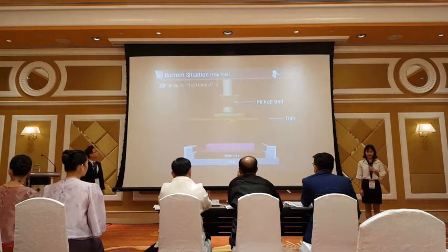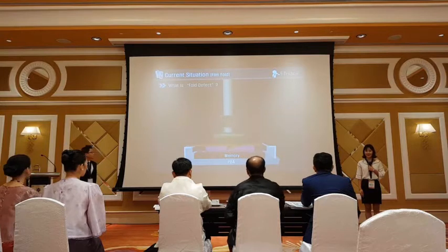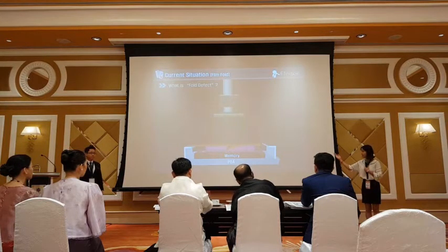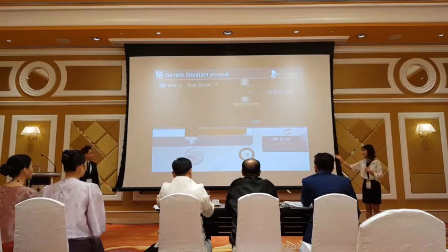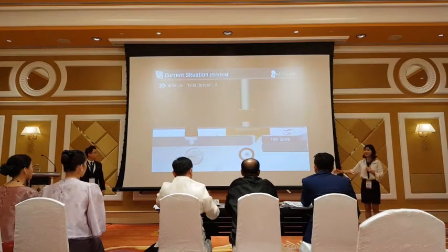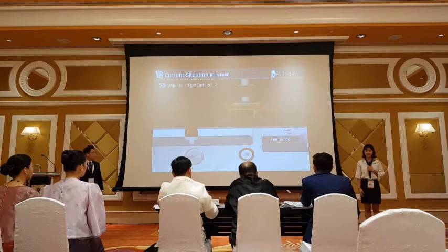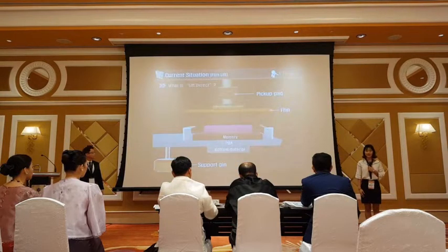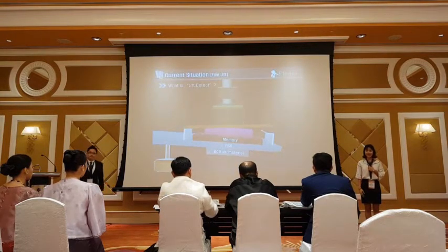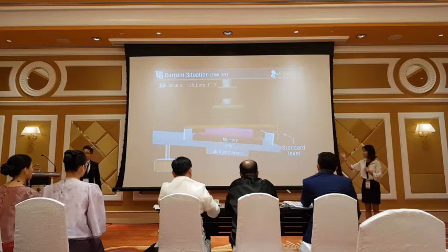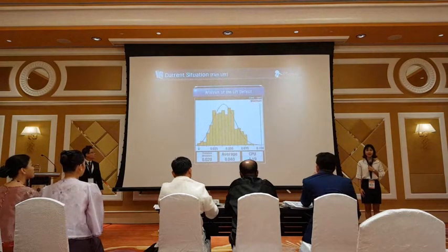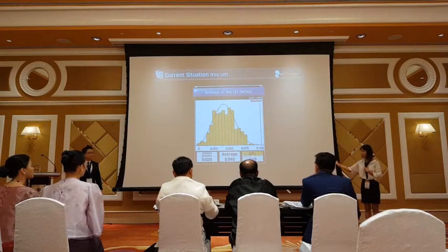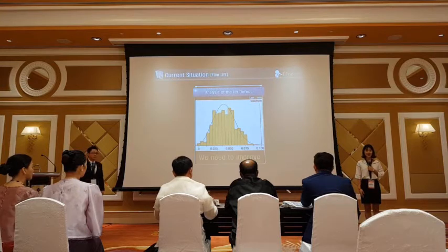What is the fold defect? It just tells that the film is not flat and is folded. When the film is applied, we confirm fold phenomenon at the picker position. What is lift defect? It just tells that the film comes off on shielded plane. Process capability analysis says the CPK is 1.19, which means we need to make modifications.